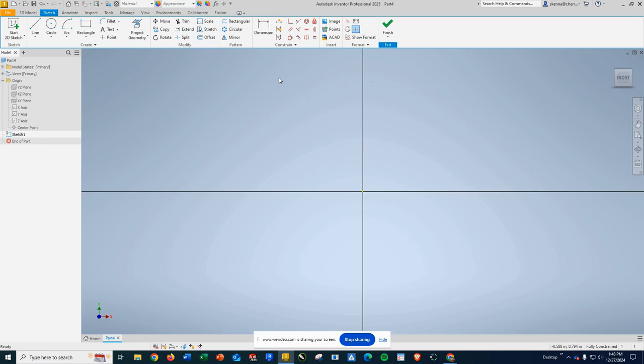Now, this software does have a color system. You will see black lines are fully constrained and blue lines or shapes are not fully constrained yet. And like it says now, with nothing created yet, it says fully constrained down here. When there are issues that are undefined or unconstrained, they will show up as one dimension needed, two dimensions needed, that sort of stuff. And you don't always have to fix them with a dimension. A constraint would also fix it as well.